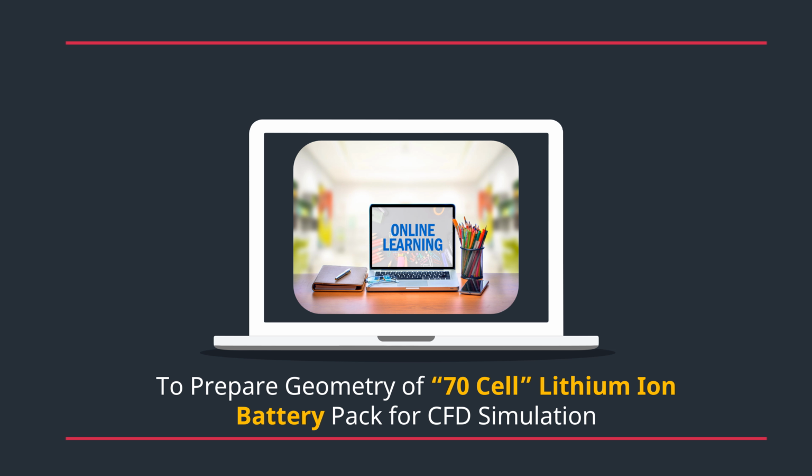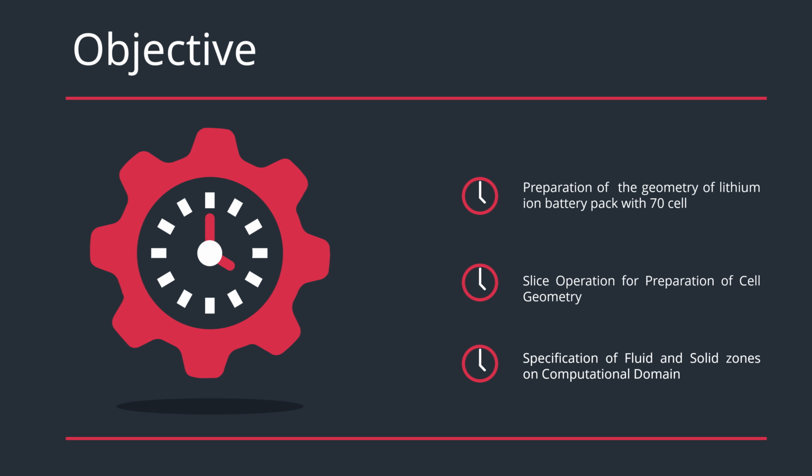Today we are preparing the geometry of a 70 cell lithium ion battery pack for CFD simulation. Today's objective is to prepare the geometry of the lithium ion battery pack with 70 cells. A slice operation we need to do, instead of a pattern, to prepare each and every individual cell. And the last operation is the specification of fluid and solid zones on the computational domain.